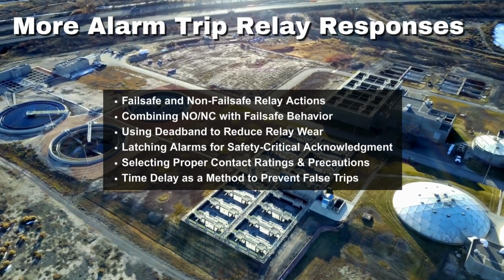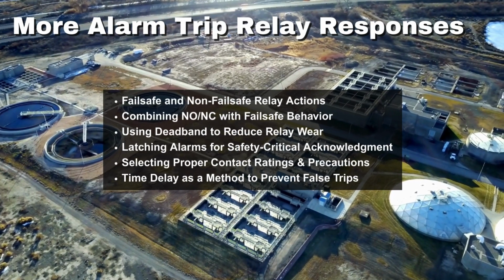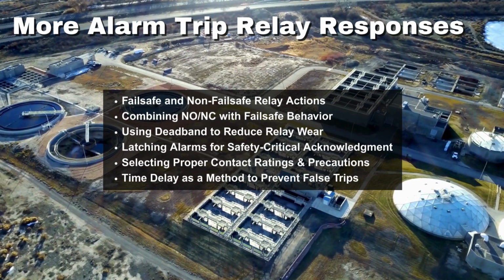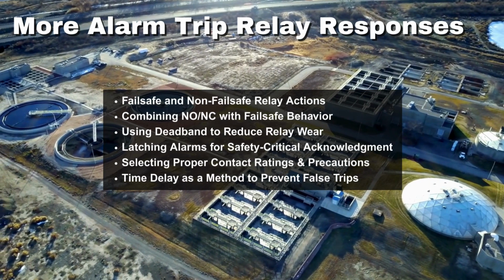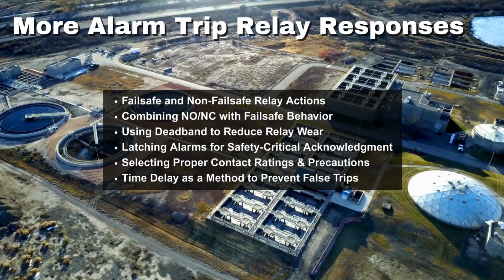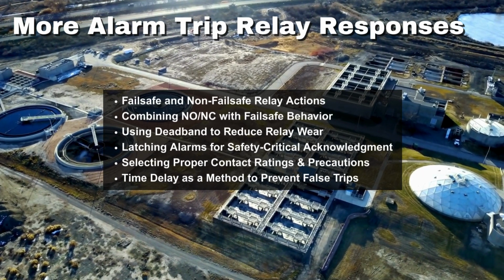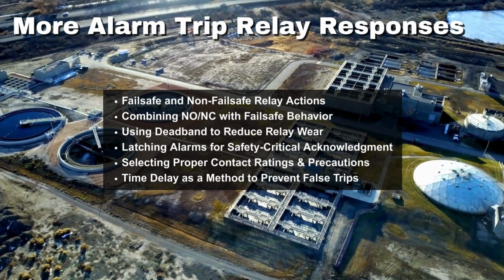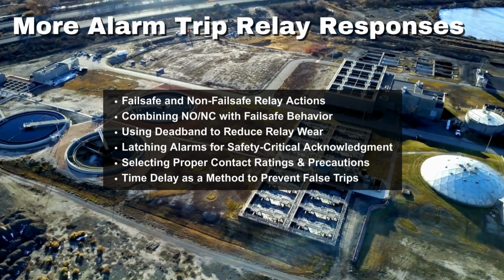In this video, we discussed how key alarm trip settings such as failsafe configurations, deadband, latching, contact ratings, and time delays affect the performance and reliability of your safety system. With the right setup, your alarms can do more than signal trouble. They can help prevent it.